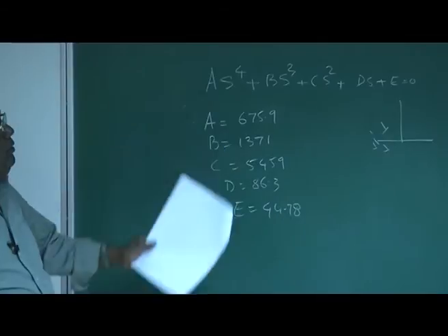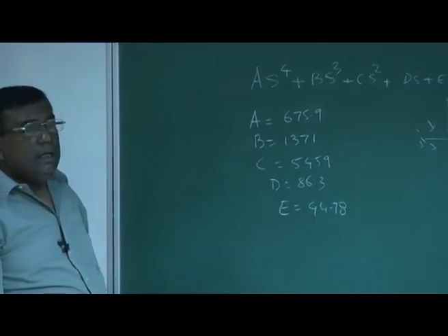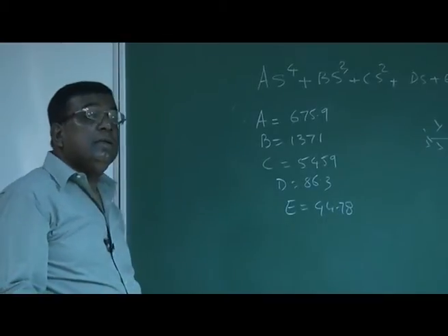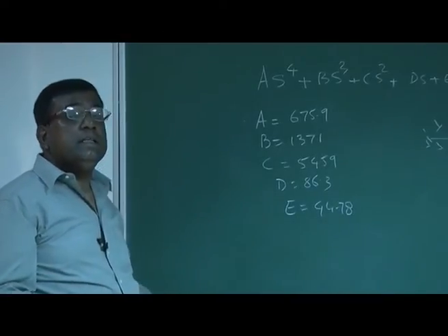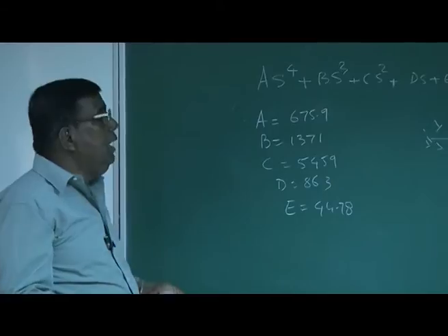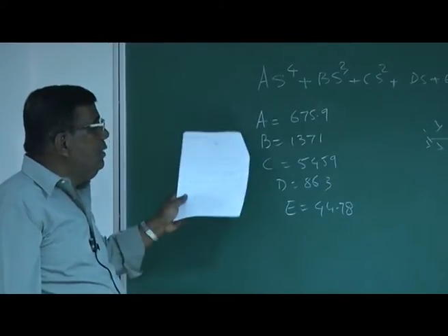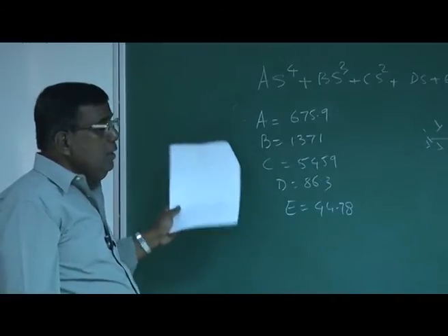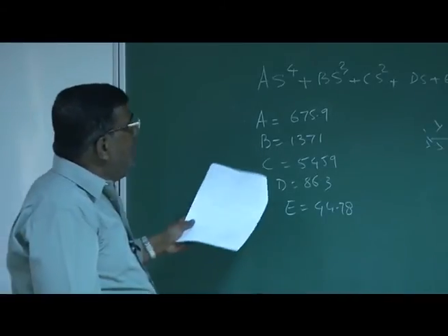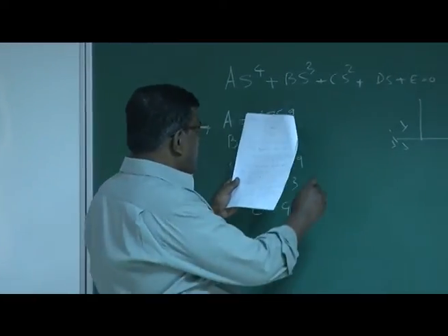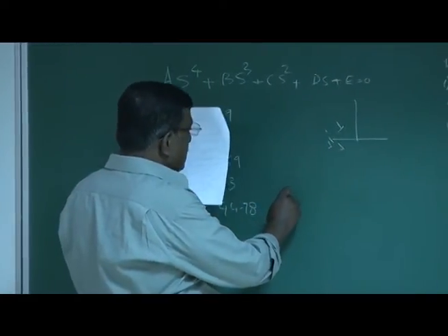You know how to calculate this A, B, C, D, E using the dimensional derivatives, or using inertia and mass properties and the aerodynamic derivatives, etc. Right? These formulae are listed, and you can refer to them. What is important is that when we solved this equation exactly, we found there are two pairs of roots.